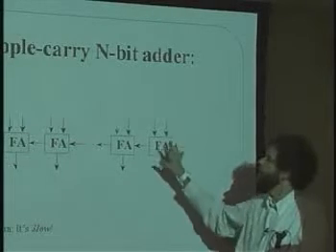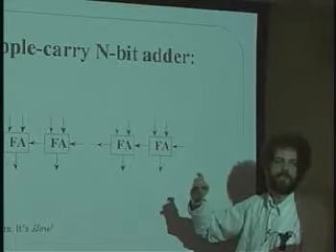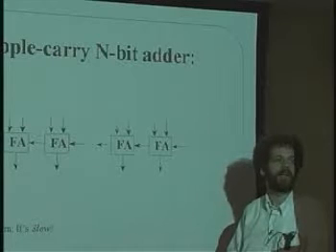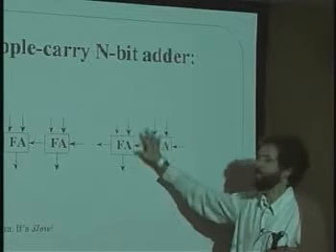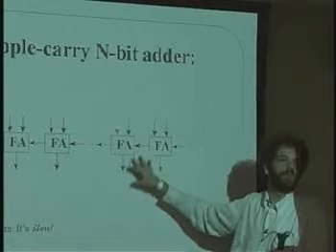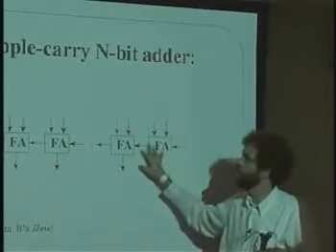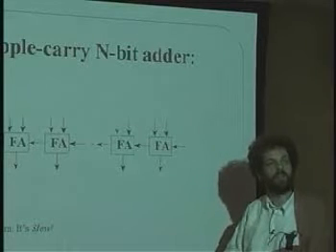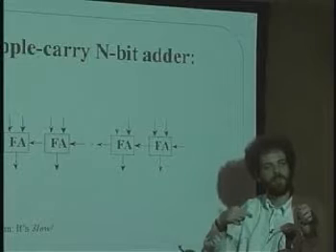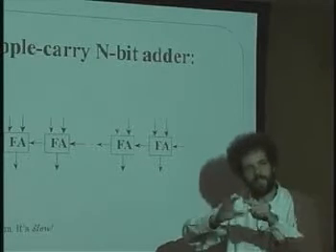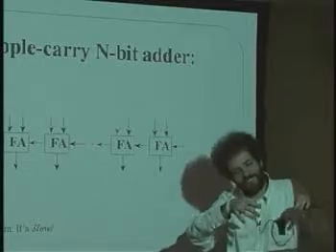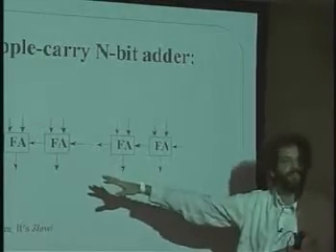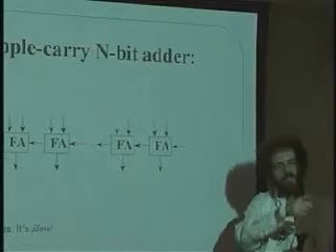So, in this simple case of just the ripple carry adder, in general, first of all, it has 2 issues. One is that it's highly dependent on what the numbers are that you're trying to add. If the carries only happen on the right-hand side, then the adder will be fast. But if the carries are required to go all the way through, it's like having an odometer on a car, and it says all nines, right? And you go over that last mile, and that last one turns the next 9, and that 9 turns the next 9, and so on. That's kind of how this full adder system works, the ripple chain, but it takes a long time for it to carry over. Yeah?